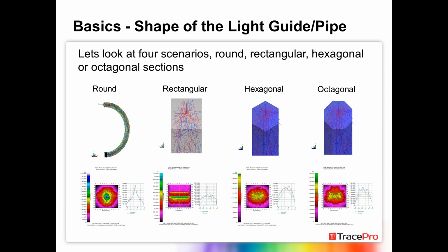Of the 2 different methods, the photorealistic render is much, much faster. It is an approximation, and that's underneath the view command, whereas the luminance calculation is an exact ray tracing using the exact colors of the wavelengths that you set up. And each one of these allows you to look at a linear scale output, a true color scale, and a log scale of that particular event that you're trying to do, either the luminance or the photorealistic rendering.